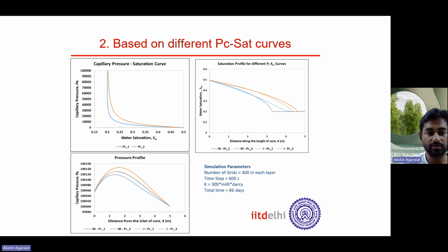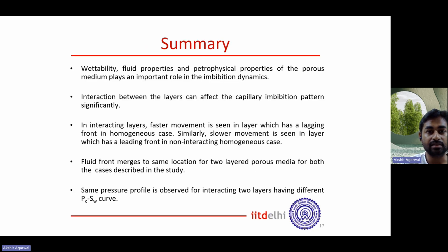Due to the time, I will not discuss the third case of different wettability cases. I will now summarize the key results of the study that we did. Wettability, fluid properties, and petrophysical properties of the porous medium play an important role in the imbibition dynamics. The interaction between the layers can affect the imbibition pattern significantly.